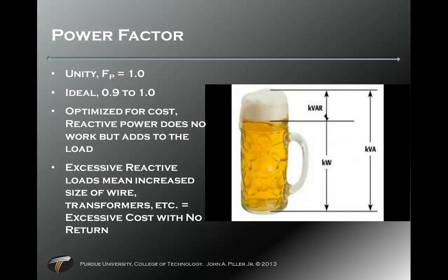If you think about the power triangle, you have S as the hypotenuse, P as the side adjacent to the angle, and Q as the side opposite the angle. So we're talking about the ratio of P to S, which, like I said, is cosine theta. If we have a highly reactive load, we end up with a very large theta, which decreases the power factor.